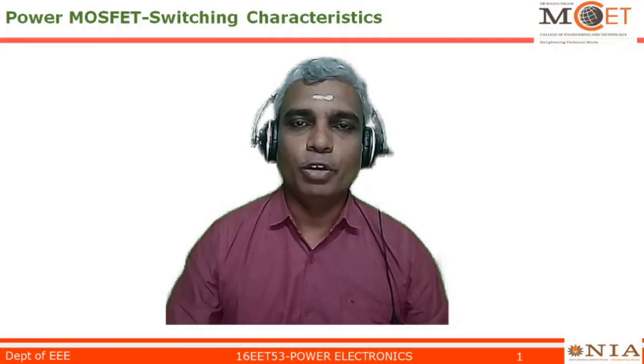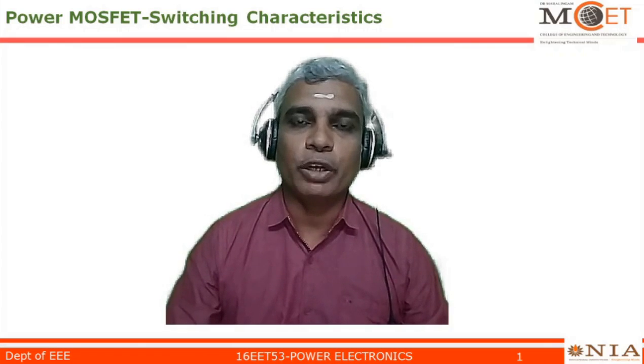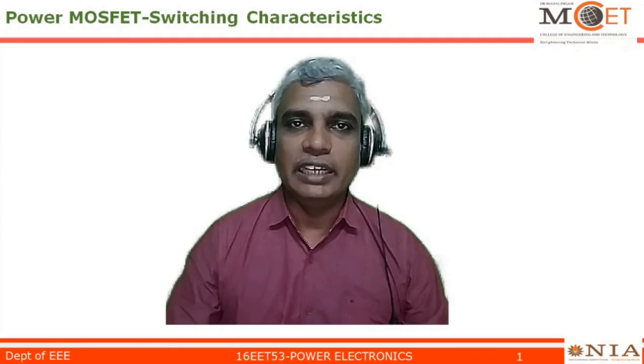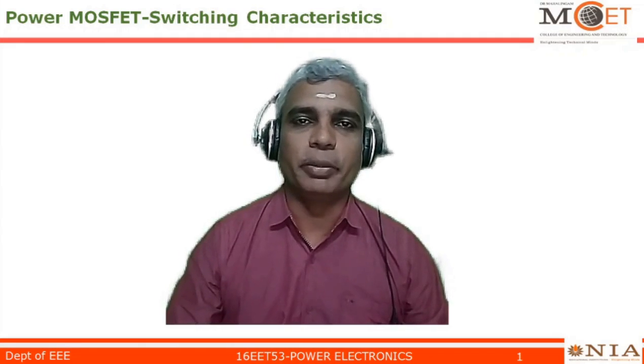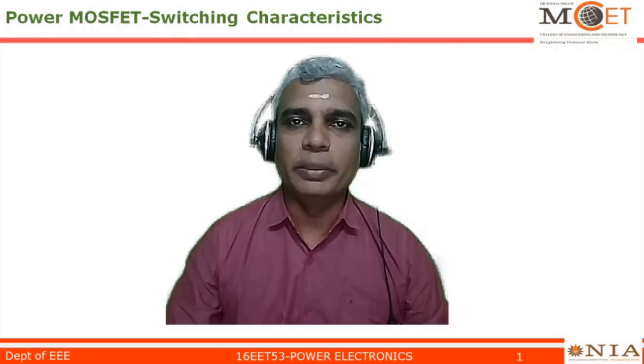In the case of output characteristics, we fixed the value of VGS, we varied VDD, we observed VDS and plotted it against ID. And during this output characteristics, we came across three regions of operation. One is the cutoff region, where the device is completely off, and the next one is the ohmic region, where the device has a linear relationship between VDS and ID.